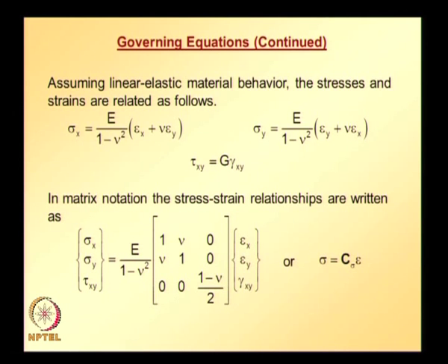C subscript sigma denotes the constitutive matrix corresponding to plane stress condition. So, we got relations between strains and displacements, and also relations between stresses and strains, for the plane stress case under small deformation and linear elastic material behavior assumption.